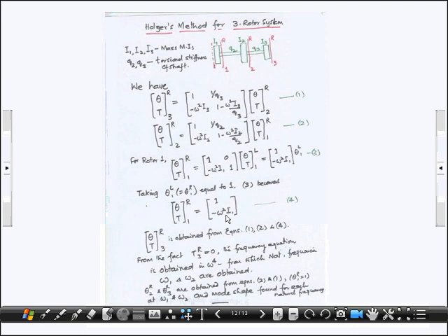With this, all we have to do now is get theta, t at R3 by combining these two equations with the knowledge of theta, t at R1. Once you do that, as we have seen earlier, we need to apply the end condition. The one end condition that will be of use to us is the torque to the right of this rotor, which is TR3.